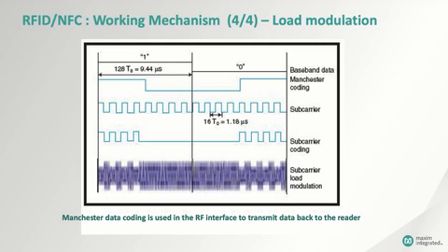The third trace represents the waveform that goes to the antenna switch. When the level is a 1, the switch is open, so is the antenna loop. When the level is a 0, the switch is closed, and the antenna loop is shorted. Finally, the bottom trace shows the RF energy that you can expect to see in the reader antenna. The reader interprets a varying carrier as a high level in the recovered Manchester data stream and a constant carrier as a low level in the recovered data stream. By decoding the data, the reader recovers the 106 kilobit per second data stream.